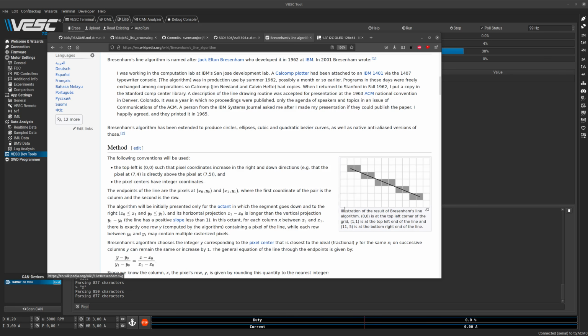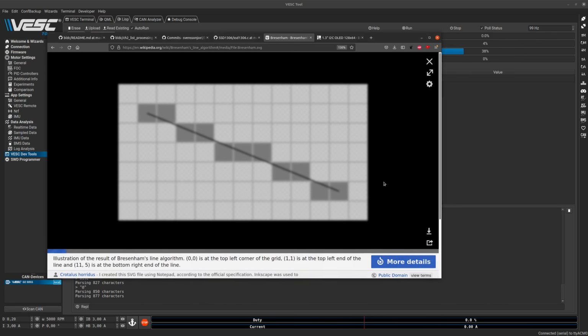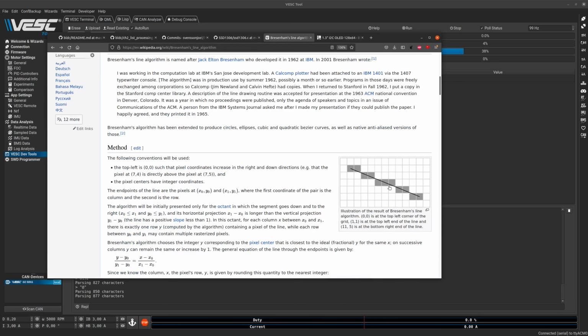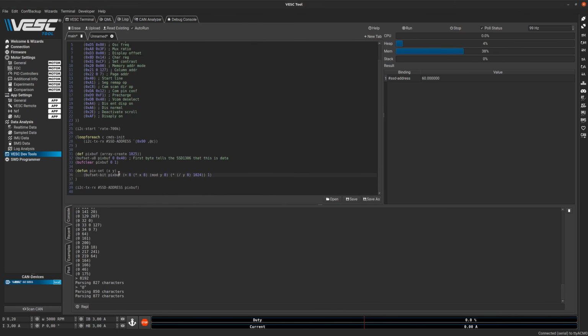And then, so this would be one byte, this would be the next byte, and so on. So if you want to set a pixel, say x is 6 and y is 4, like this pixel, then you have to set byte number 0, 1, 2, 3, 4, 5, and bit 0, 1, 2, 3 in that byte. And this is essentially the calculation that this one does. And it takes the bit coordinate for that byte, if that makes sense.